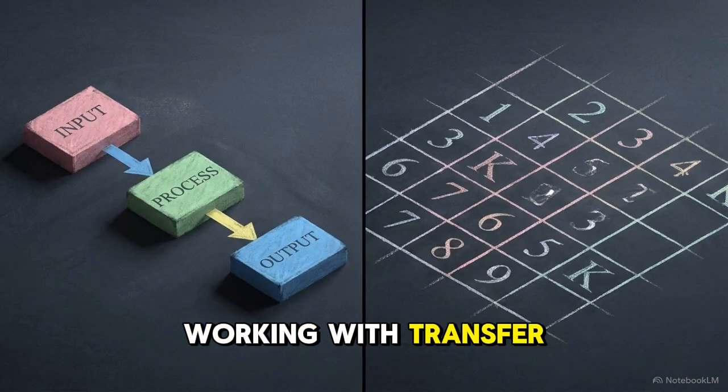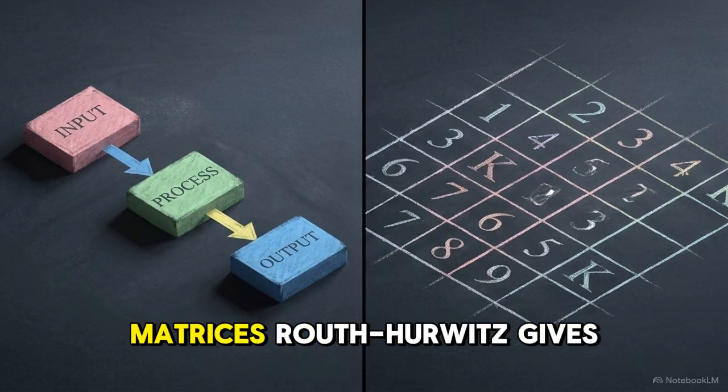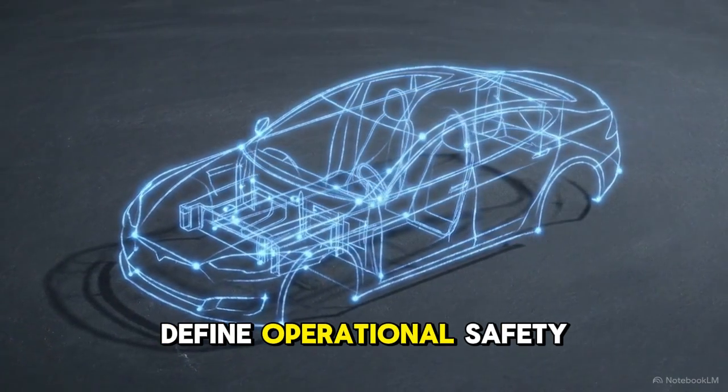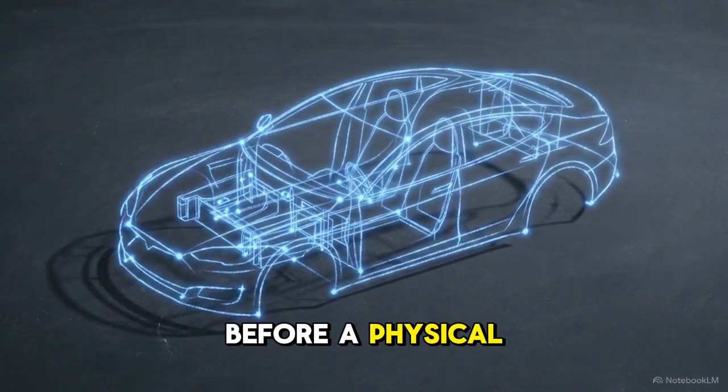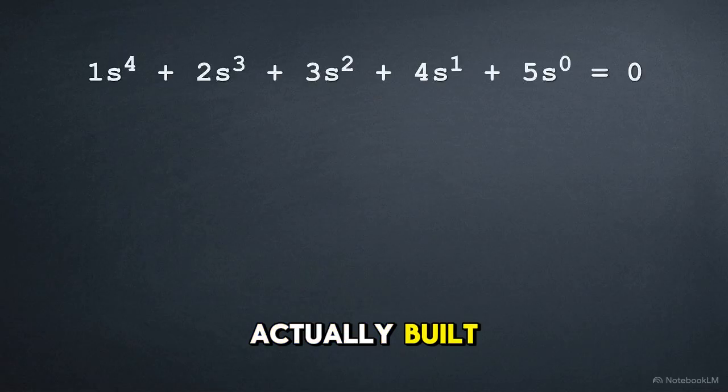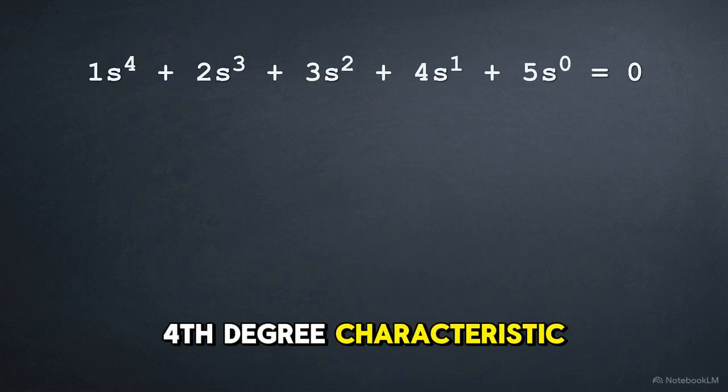Whether you are working with transfer functions or state space matrices, Routh-Hurwitz gives you a universal algebraic tool to define operational safety limits before a physical prototype is ever built or tested. Let's see how the matrix is actually built using a standard fourth-degree characteristic equation.